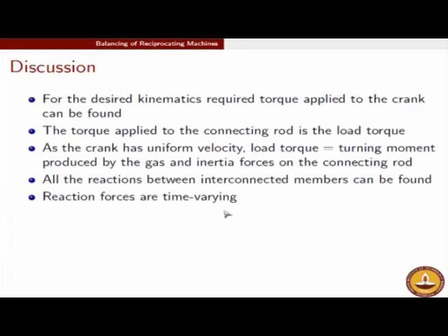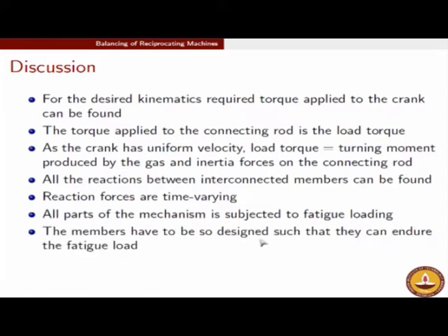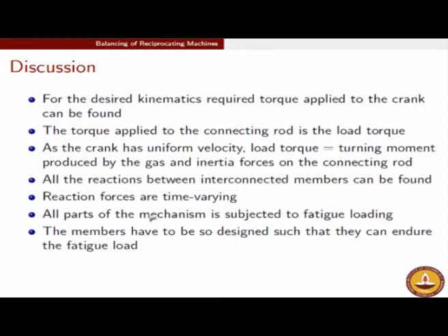Therefore the reaction forces as well as the m, which is the load torque, will be time varying. Once the reaction forces are time varying, you will see that you are inducing fatigue loading in your members, something which we have to be very careful about. The members have to be designed such that they can endure this fatigue load. So at this point, to recapitulate, we have been able to calculate the load torque, which was m, and all these reaction forces.